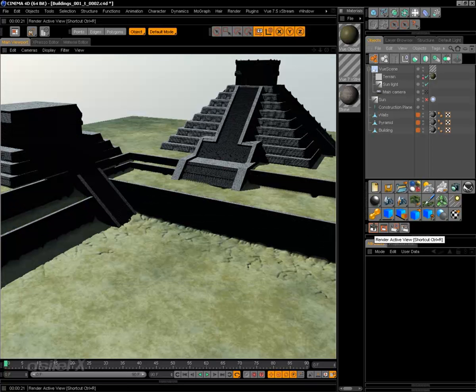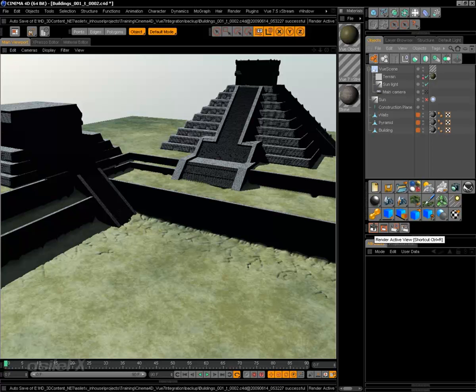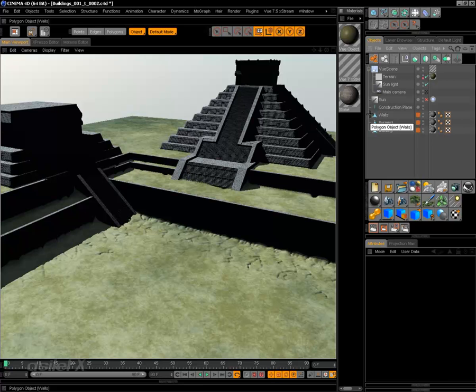So the color on the buildings looks a little better now, and on the ground it's matched to that blue color that wasn't carried over. So now what we need to do is fix the ambient light. If you're using the advanced renderer, you can turn on global illumination and use radiosity. There are a few drawbacks. For the most part, it works really well. But there are a couple of things, light bouncing back and forth between objects that may not show up correctly. We'll take a look at that in a sec.